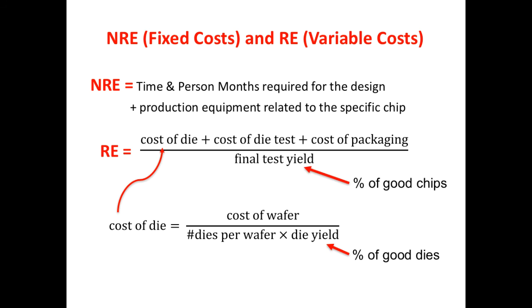One of them is the number of defects that you have per area, let's say per square millimeter. And then an additional component is the area of the die, because the point is that typically a single large defect is sufficient to make the die not usable, and of course the larger the die, the easier it is that you have a defect in the die.